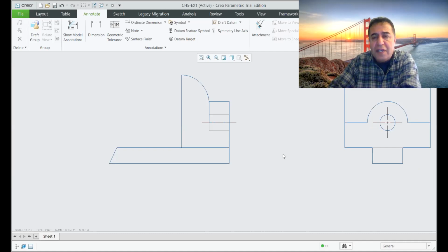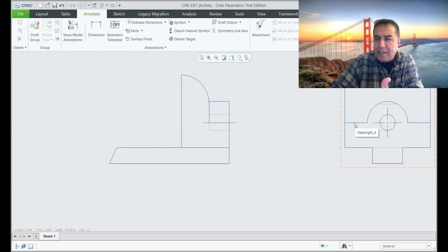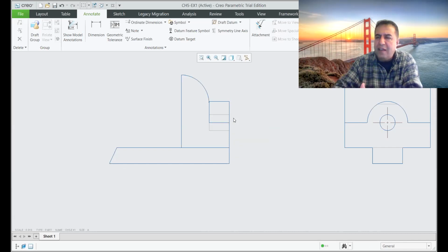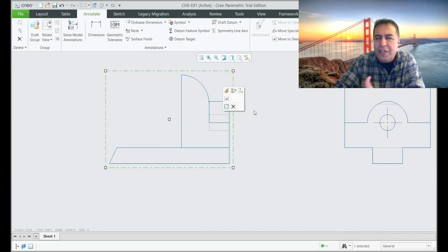There are hundreds of rules put in the book, what we call a book, for dimensioning and tolerancing, and how to add features such as center lines, hidden lines, and all that. There's an alphabet of lines. If you have a coinciding situation, the solid line and center line, since the solid line takes precedence over the center line, we don't need to show the center line. You can delete that, okay? This line is coinciding with the solid line. When you project that, we say it's underneath the solid line. You don't need to worry about that.